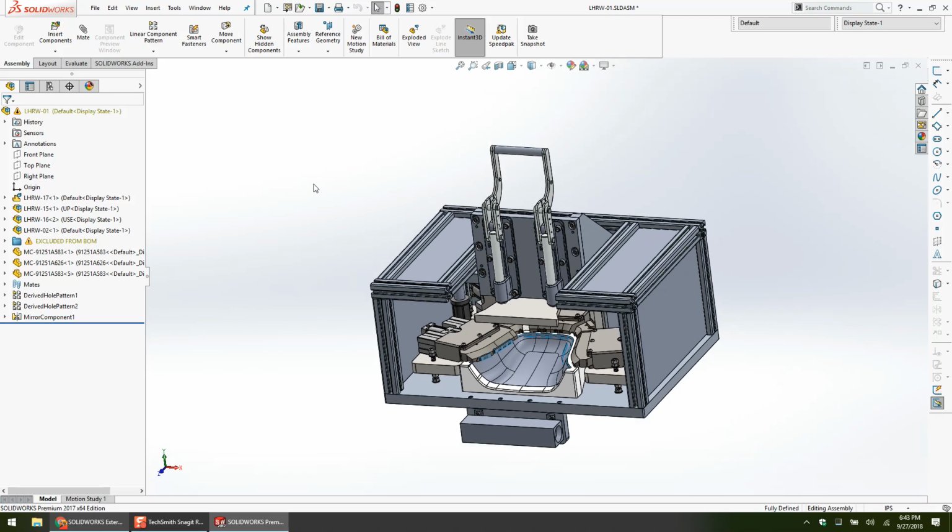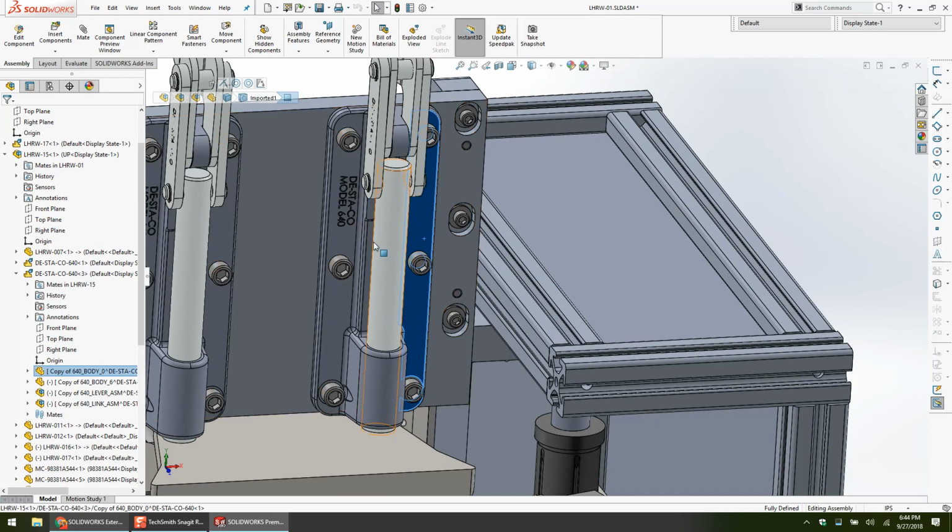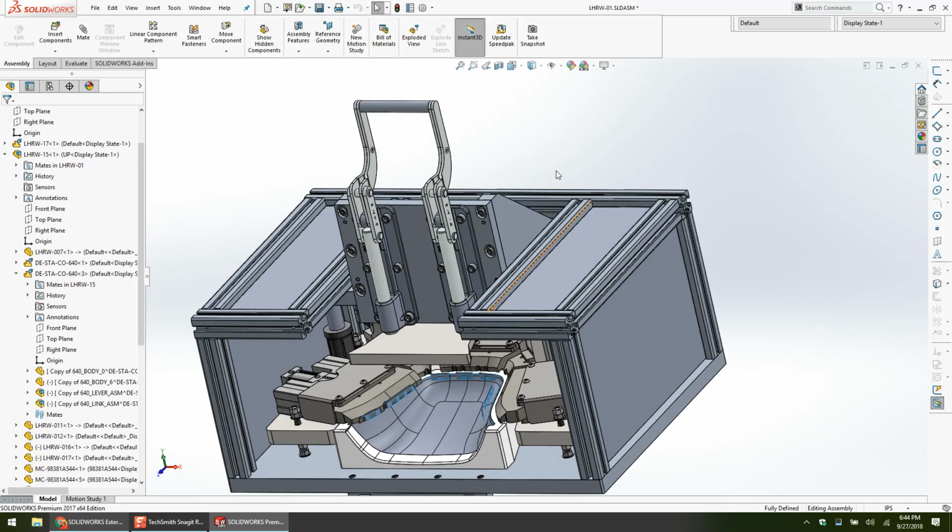The reason it's such a good fit for purchase commodities is because they never change, right? The Stego clamp simply cannot change the geometry, or at least the critical geometry of this clamp. Otherwise, they can never sell a replacement part. So when you download a purchase component, you're absolutely guaranteed that geometry and part number, as long as they keep selling it. Sometimes they obsolete it and say, here's a new thing. But as long as they keep selling that model or a similar model, you know the geometry is going to be stable, and then you can just virtualize it and run it for life. I wouldn't virtualize stuff when it's subject to change. That's kind of playing with fire.